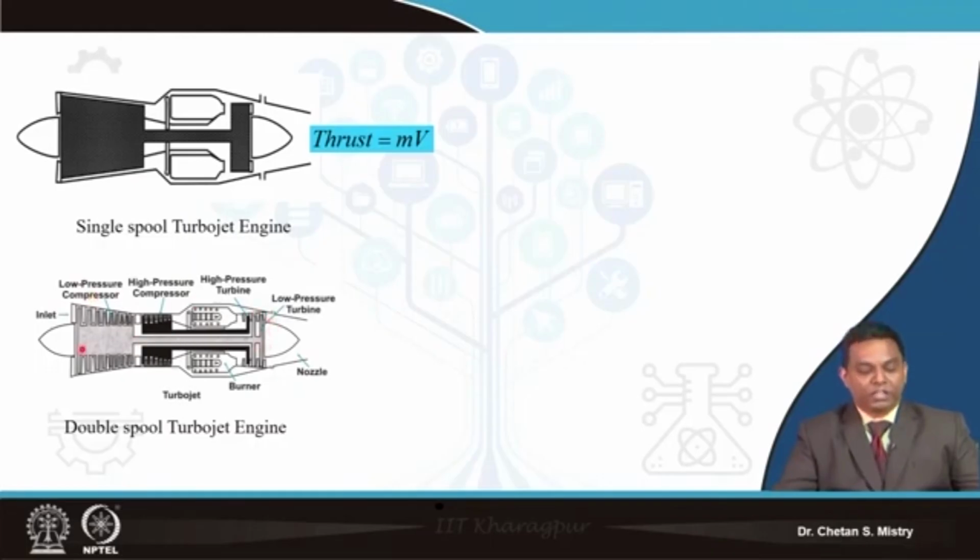Now here in this case, do not get confused with the terminology of low pressure. It does not mean that the compressor stage is generating low pressure. You need to understand my operating pressure is low, and that's the reason why this is called the low pressure compressor. Now if you look at the rear side, this spool is called the HP spool, which is rotating at high speed.